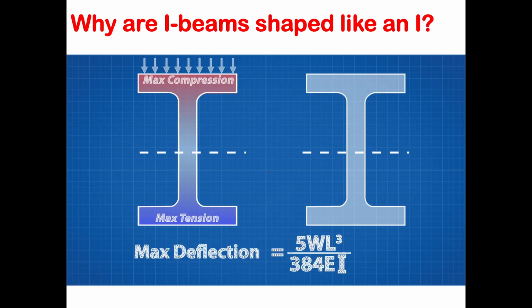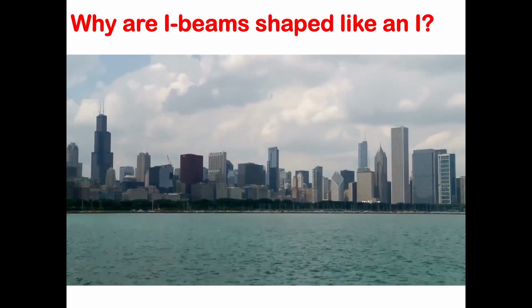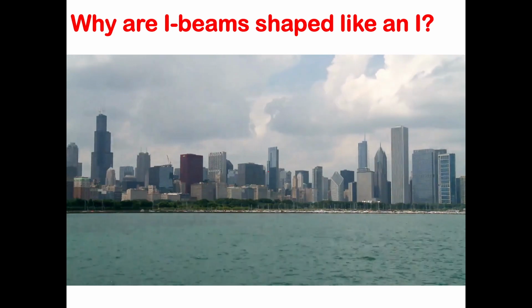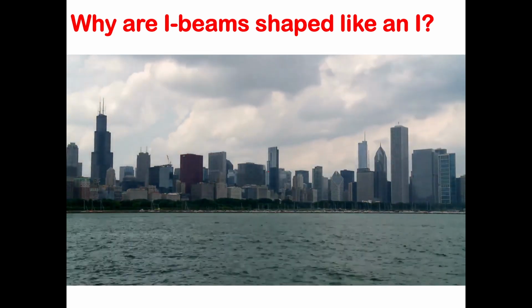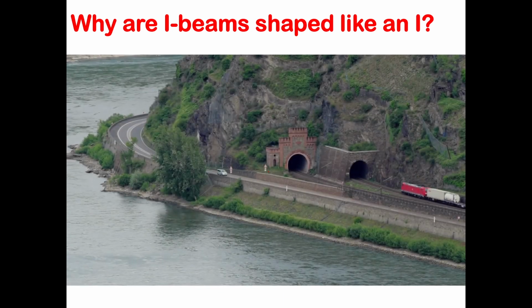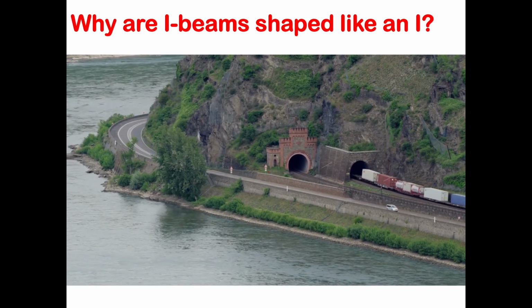You can see this idea put into action all around you. In my last video, I mentioned just one of them, when I spoke about the Willis Tower using a bundled tube structure. This structure maximizes the amount of steel on the outside of the building to maximize its resistance to lateral bending from wind and other loads. I will be talking about another application of this technology in my next video, and if you can think of any other examples of this.